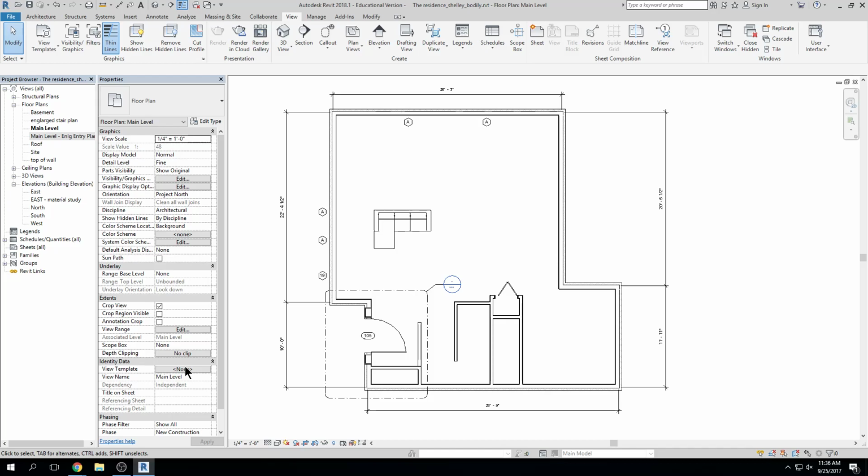All right, so views, we can duplicate them, we can visually manipulate them separately to see different things, right? We can manage what we see on our views using our view range, okay? We can create call outs of views that essentially create a brand new floor plan, right? That crop a certain area where specific work is going to be done, like an enlarged floor plan or, you know, an enlarged stair plan, whatever you want to do, or a detail, okay?